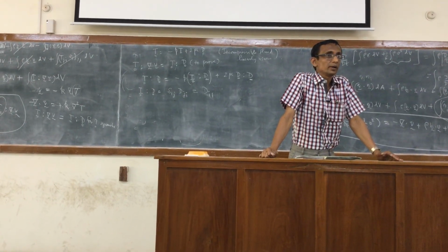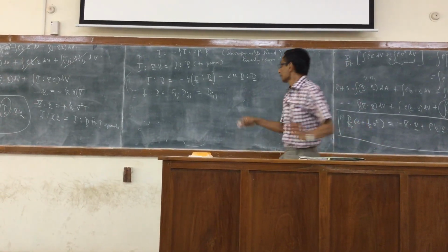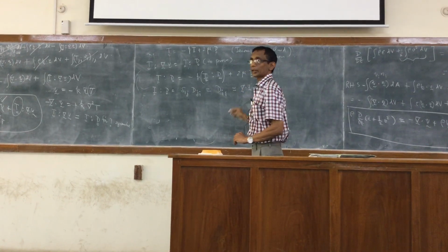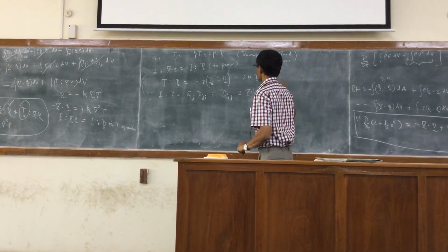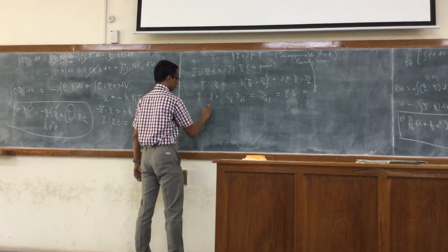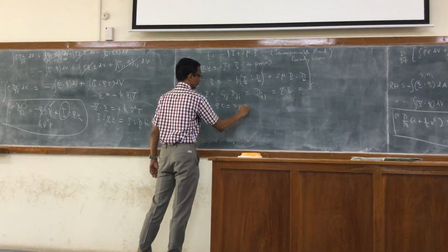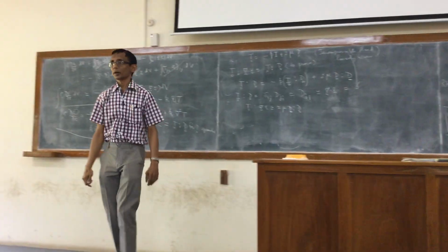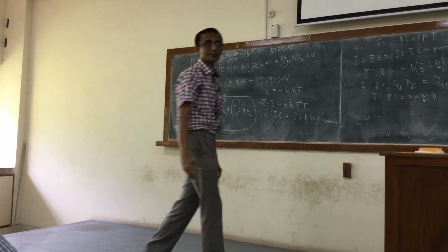What is it for an incompressible fluid? It's 0 for an incompressible fluid, it can be easily shown, we have already shown it. So this term doesn't contribute, and this is applied only for an incompressible linearly viscous fluid. So we get this simple form for the viscous dissipation term.